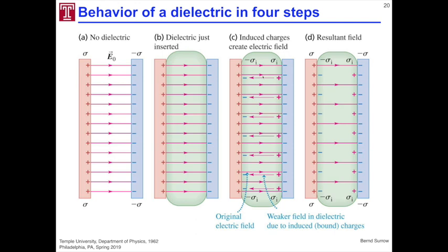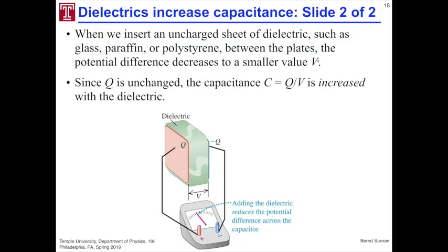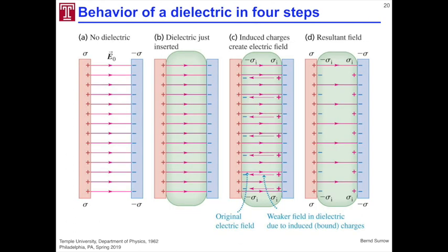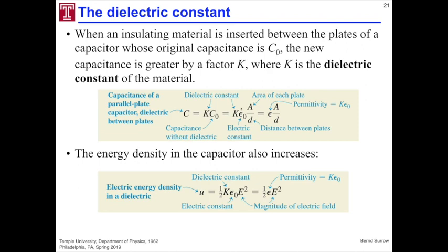You can answer this for yourself. You see this graphically, that the net resultant field is somewhat smaller. So the resultant field, let's go back here. The resultant field is smaller, the electrical potential is smaller, but the capacitance is overall larger. So now you can tune, depending on the type of material in between here, and therefore change that capacitance value. And not only depend on the geometry, but you can tune this over a wide range using different materials. And this is what is summarized here.